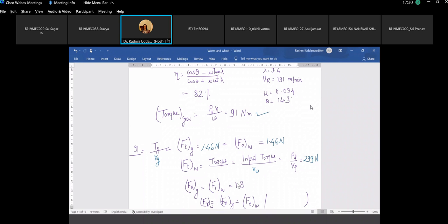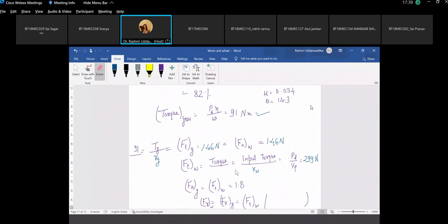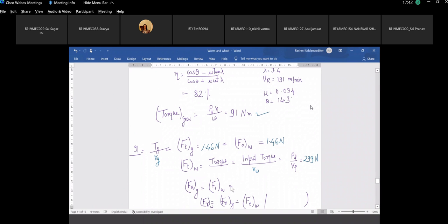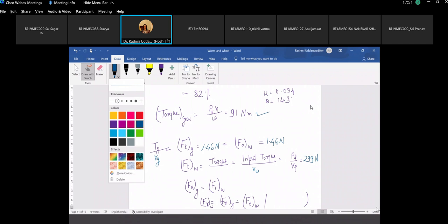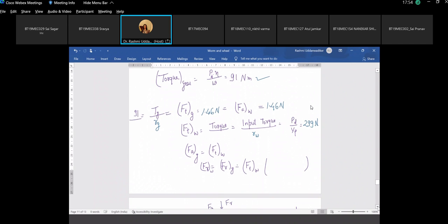And this radial force for the worm and the gear, using the formula for Fr in terms of Ft, omega, cos theta, cos lambda, sin theta. This value comes out to be 0.38 kilonewton, right? What was this value? Something like 380 newtons. 386.29. Okay, 386.